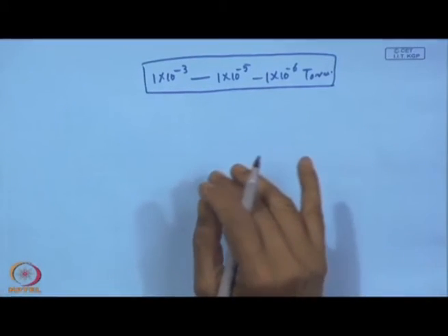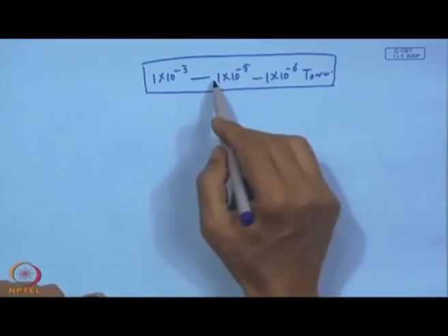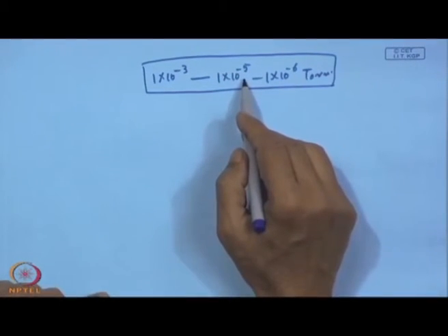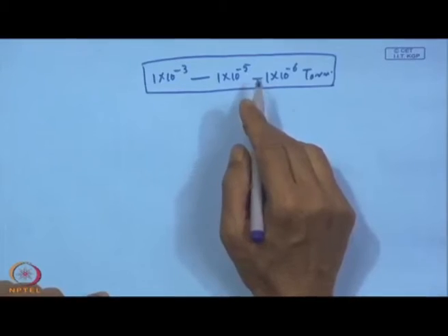So, this is the pressure, and to record it, that means evacuation of the system to this pressure, we must need a very reliable system, and for that we have the ionization gauge, where the ion current versus the residual pressure will be recorded, and that will be reliably used as a measure of pressure.